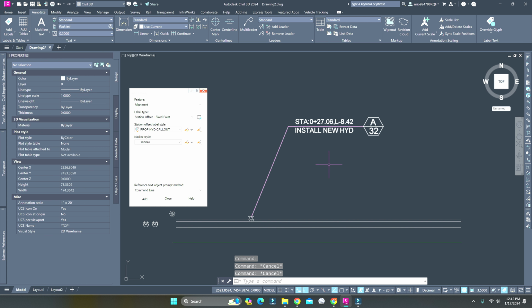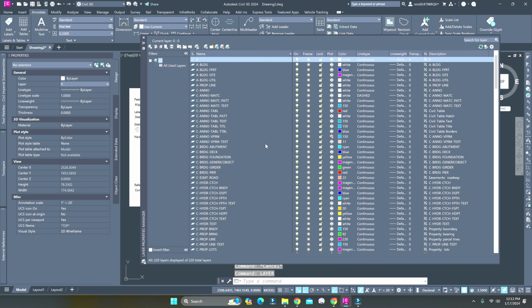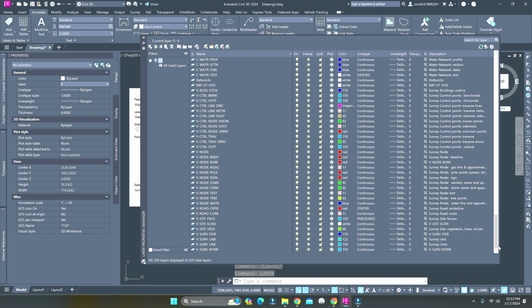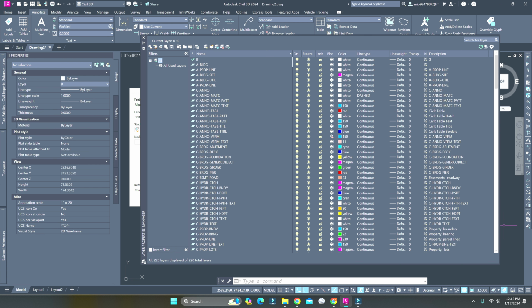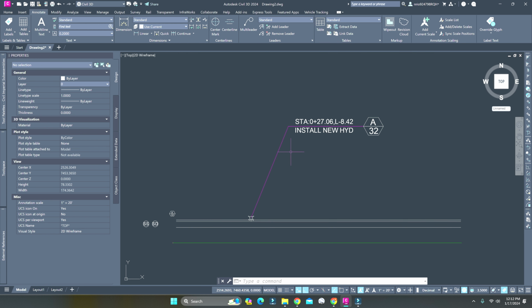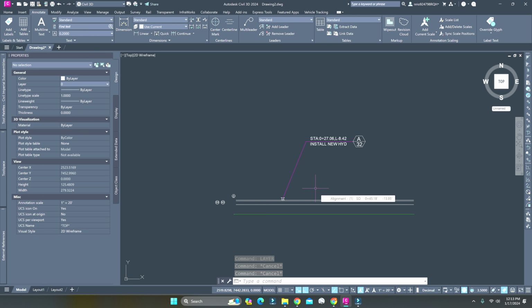improvement plans. And then X, like we did in the topo, means existing. And that's what the layer naming is calling out here. That's what all these letters are for. We use V sometimes for existing as well, and then A and building, stuff like that. They all have their own purpose, their own format of doing things. It's superficial, but yeah. So this is how you make a block, how you make a label on an alignment line, and how to attach that block to your alignment.